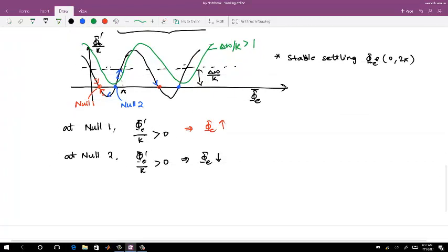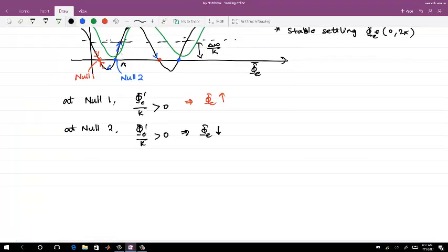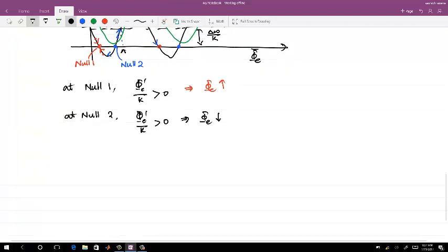Okay. So now you have seen that there is a certain range of frequencies which it can lock to. Locked means that even when there is an initial frequency error, it still locks. And if it locks, then it is a stable equilibrium. If you change anything, it will come back to a stable equilibrium with that error.